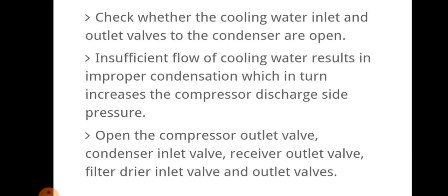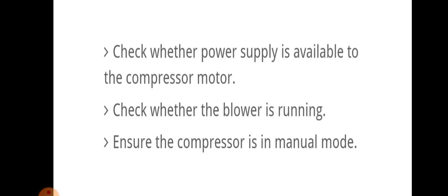You have to check whether the cooling water inlet and outlet valves to the condenser are open. Insufficient flow of cooling water results in improper condensation, which in turn increases compressor discharge pressure. And we have to open the compressor outlet valve, condenser inlet valve, receiver outlet valve, and filter dryer inlet and outlet valve.